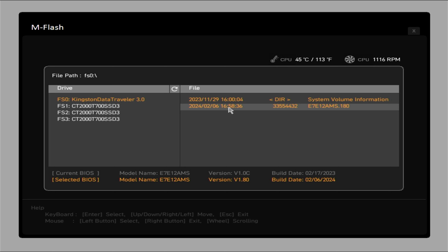So the whole idea behind one of these things is that we have different fan headers on the motherboard. So we've got our CPU fan header connected here, and one of the things I really love about it is this is real time. So if I just go ahead and connect another fan on one of the system fan headers, you will see that system 5 fan header has just fired up, and we have an RPM reading for that as well. So there is a whole bunch of stuff that you can do in here, but the main one that you want to tweak is the smart fan mode.